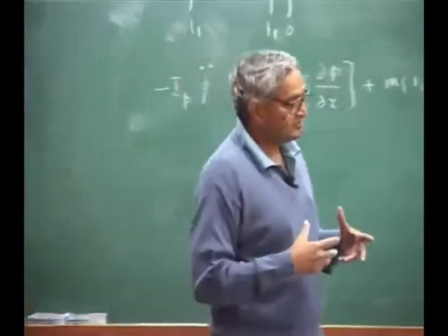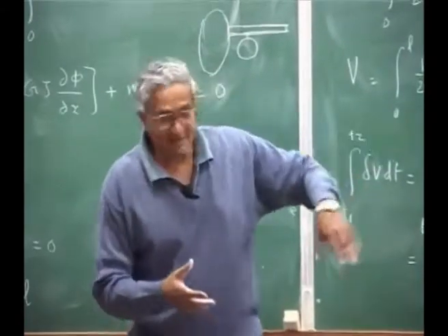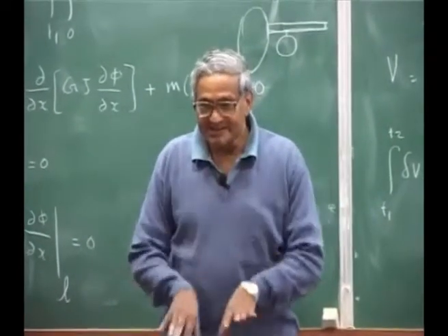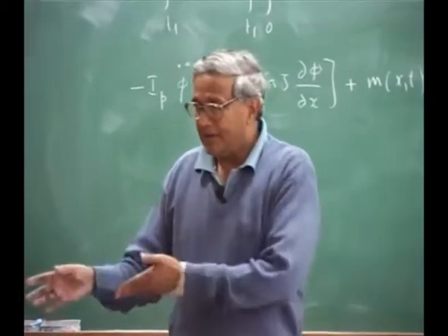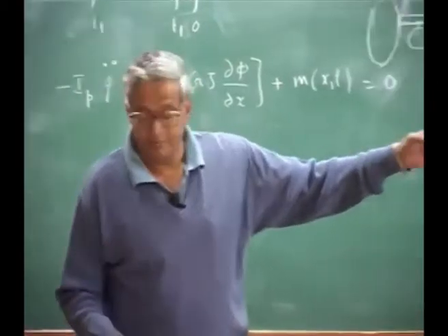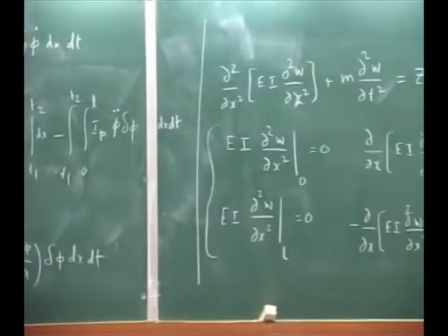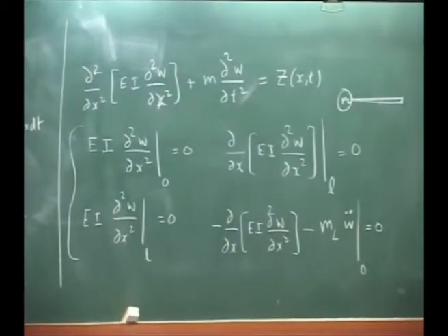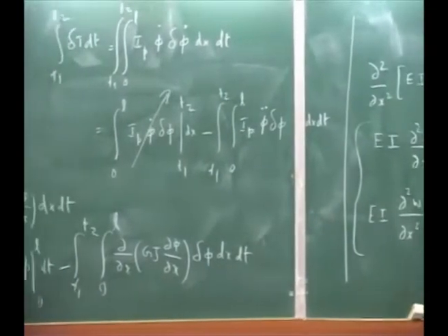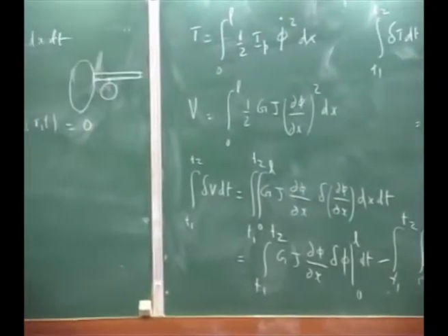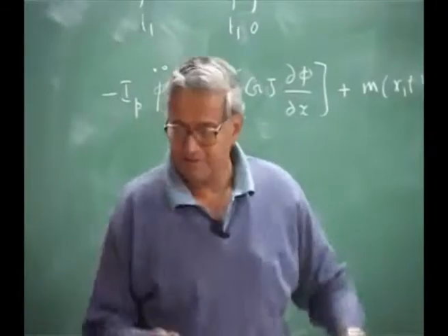Now that is where you get a free vibration problem. First you have a partial differential equation, you convert it into an ODE, and then you have to know how to solve that ODE. You follow? And that is not your only aim, because you need to find out what will happen to the beam when you have an external load also. That is a response problem. But for studying the response, you need to first know the free vibration characteristics of your wing or your entire aircraft. Okay, because that is essential to get to the response problem. So you need to study how you get the free vibration solution, and that is where the PDE is converted into an ODE.